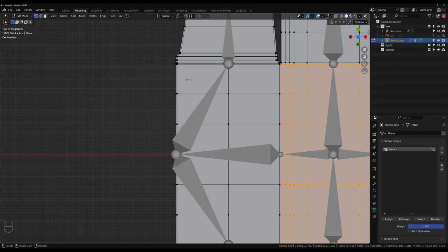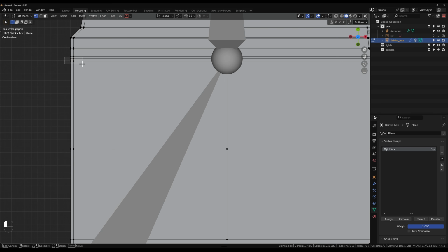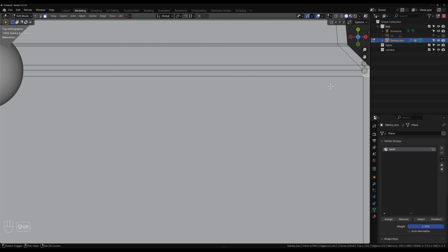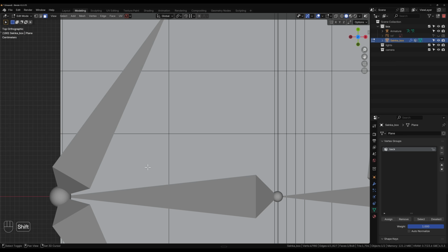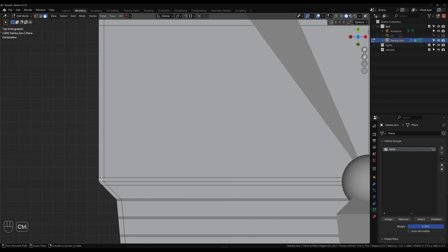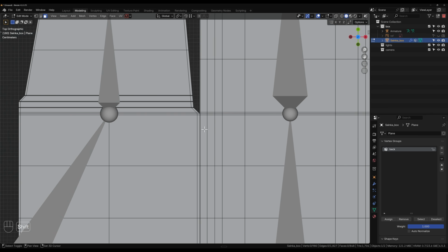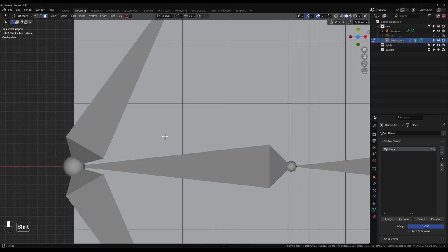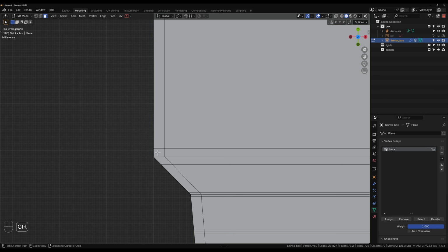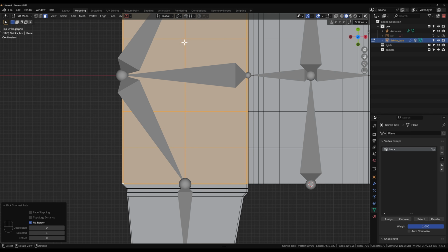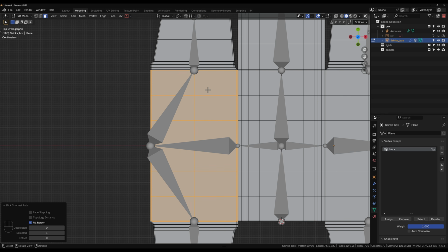And then I'm going to go over here, and what I'm going to do is select all the vertices that are within. So what we can do is select this corner here. You'll see here. Then we want to come down here, control click to this corner. Sorry, let's redo that. Select this corner just by left clicking, come down to the bottom, control shift click this corner, and it will pick the shortest path while filling the region. So I'll just select a big square. Let's press 1, have a look at the vertices that we have selected.